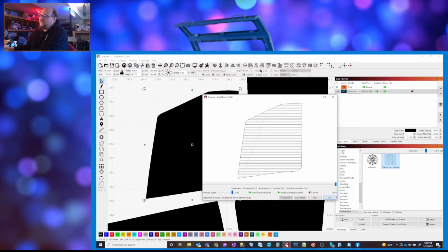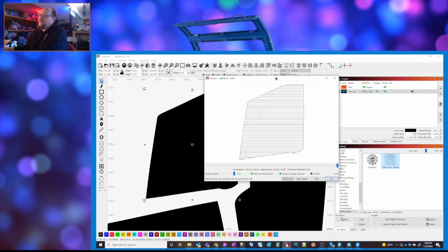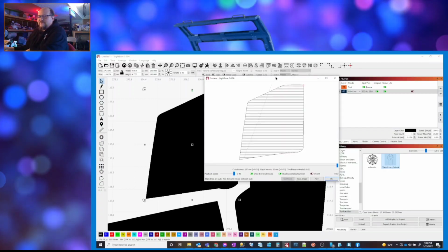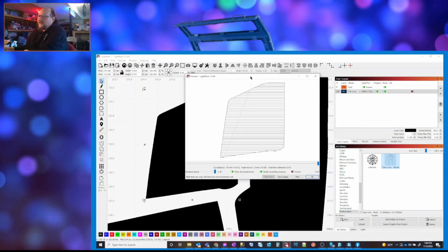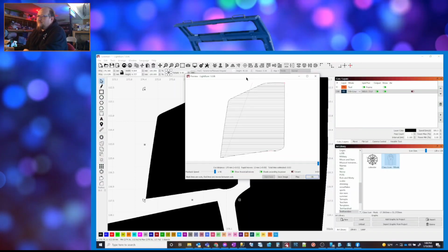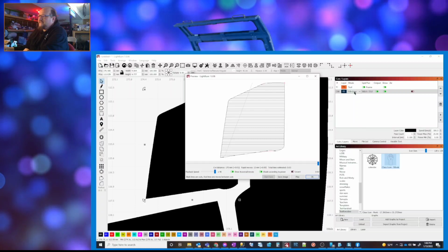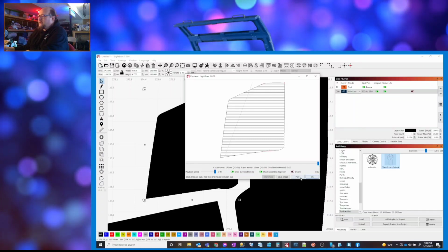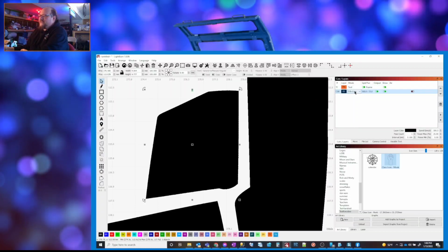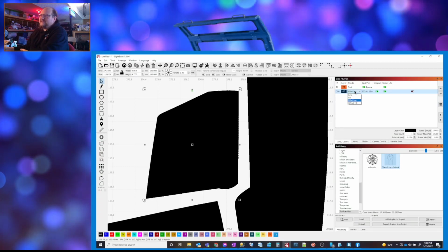I don't ever do that for the most part. I did it when I first got the laser until I realized that my offsets weren't entered. Once I entered in my offsets, I never had to do that again because the engrave works the way it should. Okay, so that's fill and fill plus line, but there's this last one that says offset fill.